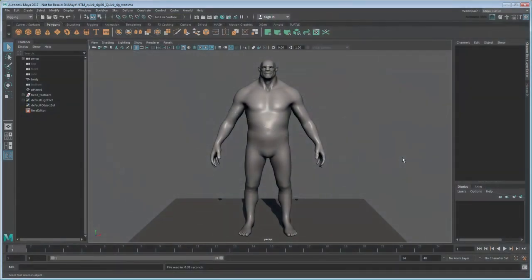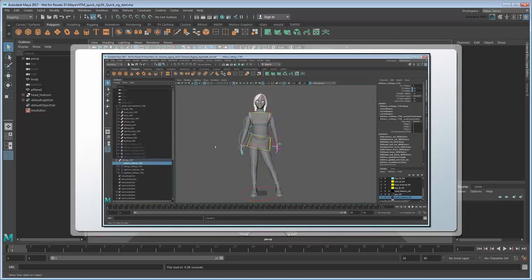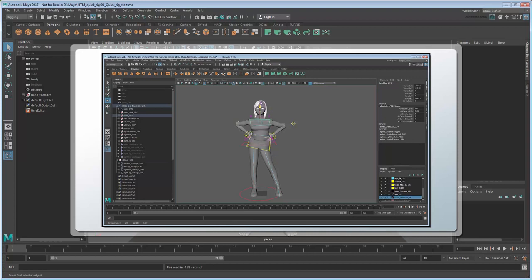The process of rigging a 3D character can often be long and complex, depending on what you expect that character to be able to do. In our comprehensive Creating a Character Rig tutorial, we showed how to create a character with full FK/IK skeletons, squash and stretch appendages, space switching, custom controls, and more.